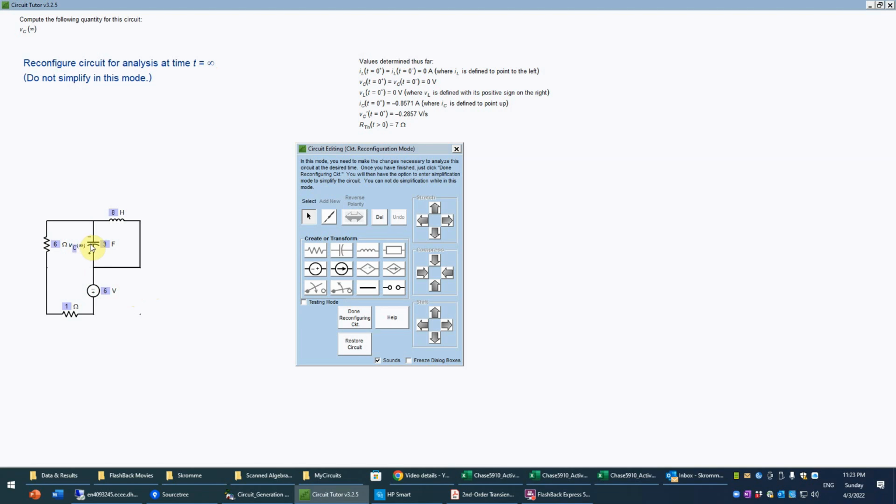And then the capacitor, whose voltage we want, that's now, because we're in steady state, i equals C dv/dt, so that, of course, is an open circuit in steady state. Okay, so at 0 minus or infinity, we're in steady state. And the inductor, likewise, is going to be a short circuit because, once again, we're in steady state. v equals L di/dt, so that has 0 voltage. So it's a short circuit. And you may say, well, that's shorting out the capacitor, which is true, but that's just what the circuit does. So we have no control over that.